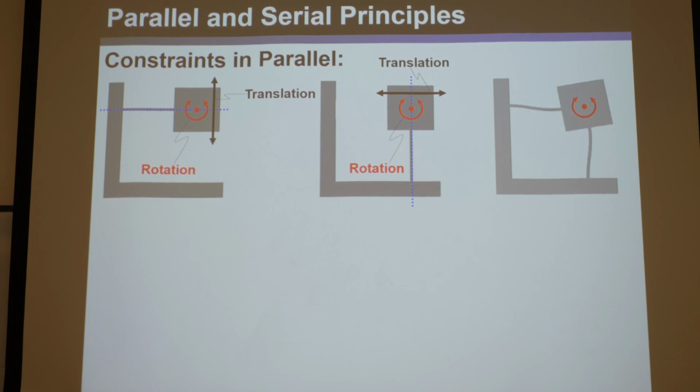This is basically the rule I told you. Remember when I held up those models we made, and I said, imagine all the wires had disks of translations perpendicular to them, and find what translations from all those disks they have in common, and you'll find the translation of the mechanism. That was essentially this. I was saying find what they have in common. Visualize